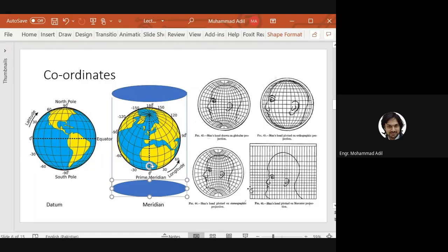So like a point on a Cartesian coordinate system, if it is at 10 meters on the x-axis and 50 meters on the y-axis, we will be saying it is 10 meters east and 50 meters north. Another big difference from the Cartesian coordinate system is that in the Mercator system, the grid is squarish near the equator, but it becomes extended rectangles towards the north and the south.